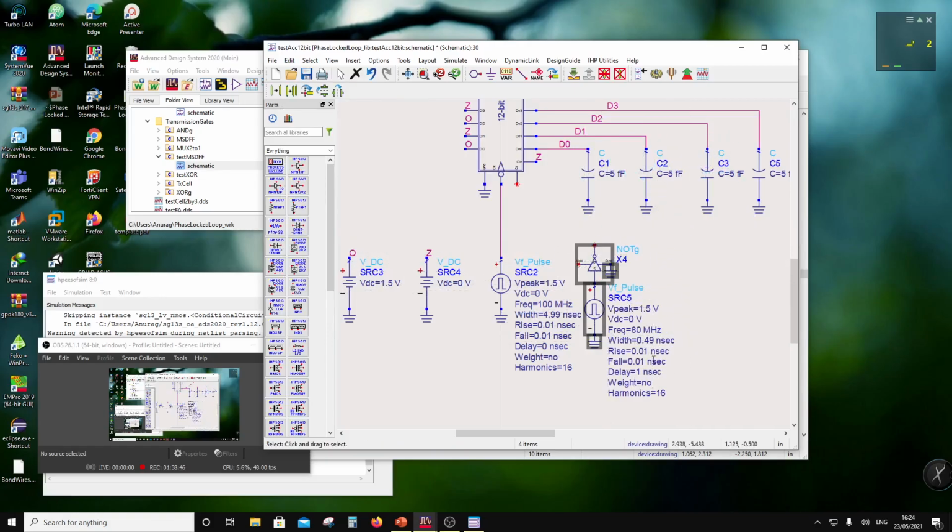Okay, so let's see what's happening here. I'm going to put here, let's say, limiting case 1 kilohertz, for example. So every time when I'm loading it, I'm introducing a pulse which is going to be this wide, and then it's going to have this rise time and fall time, fine, and then the delay is 1 nanosecond.